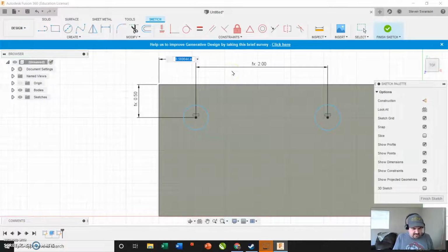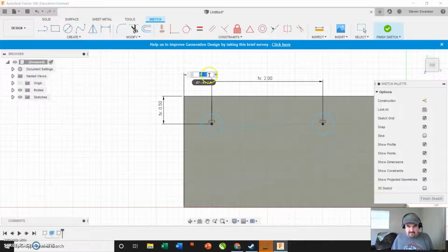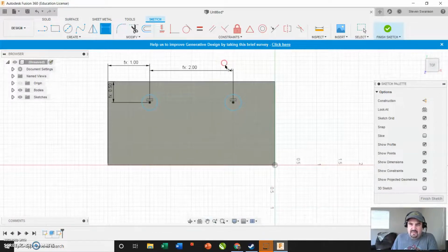So I'm going to put actually D1, that's that first dimension, divided by 8. There we go. That's not centered. I'm going to do it divided by 4, and I think that will center it. There we go. Yeah, so that's fully centered. So now everything is parametrically constrained.